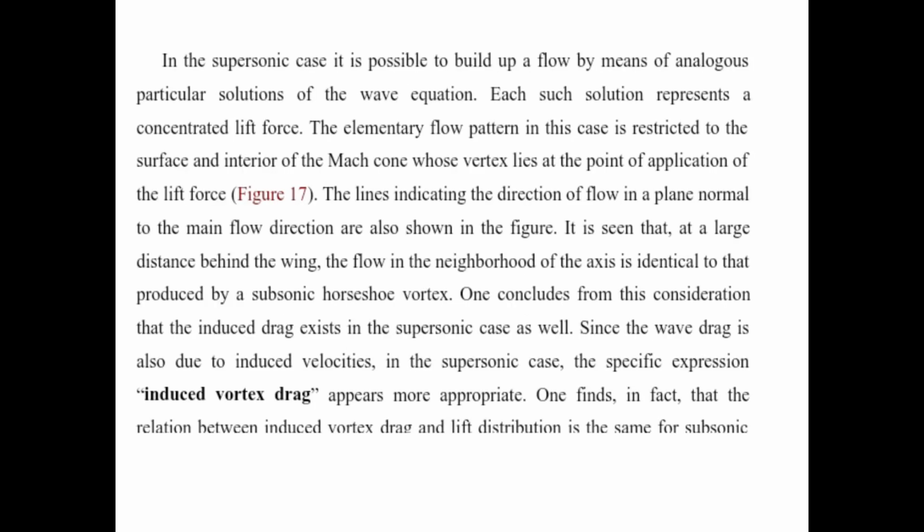In the supersonic case, it is possible to build up a flow by means of analogous particular solutions of the wave equation. Each such solution represents a concentrated lift force. The elementary flow pattern in this case is restricted to the surface and interior of the Mach cone whose vertex lies at the point of application of the lift force.